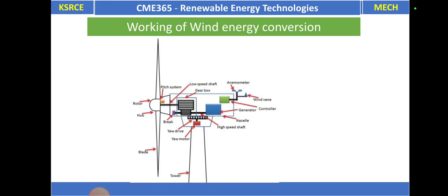A tower produces turbulence behind it. The turbine is usually pointed upwind of the tower. Turbine blades are made stiff to prevent blades from being pushed into the tower by high winds. The blades are placed at a considerable distance in front of the tower, and they are sometimes tilted up a small amount.